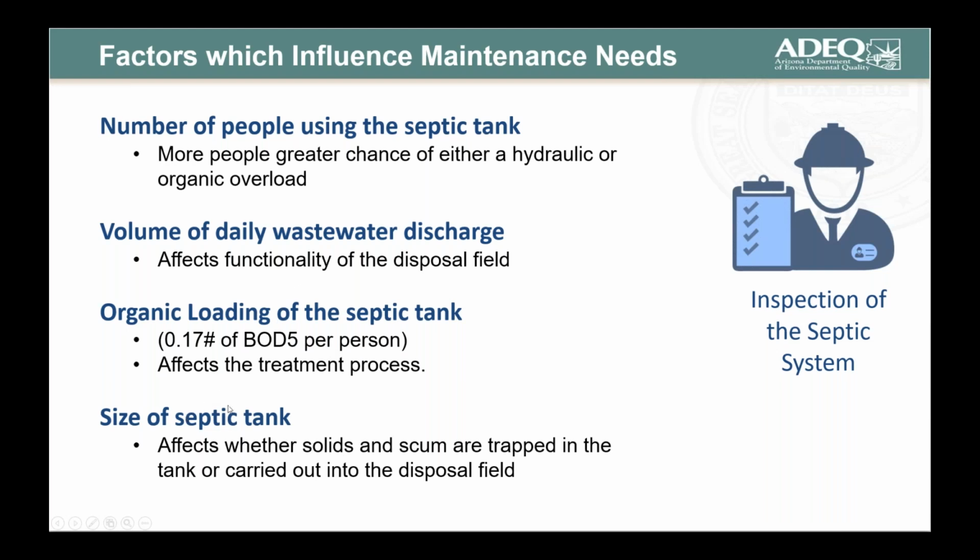The size of the septic tank is not only related to the organic loading of the septic tank, it's also related to the volume of the daily discharge. Because if you have a large volume of wastewater going into the septic tank, and especially if the septic tank is undersized, you will not get a 2.1 day detention time. You will get something less than that.